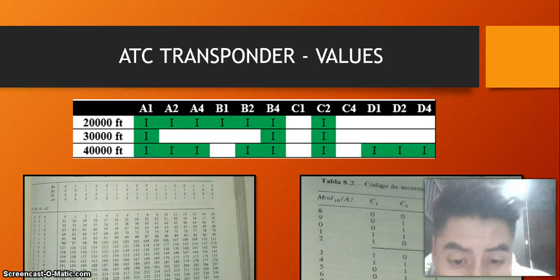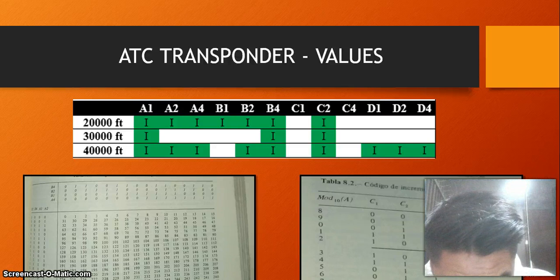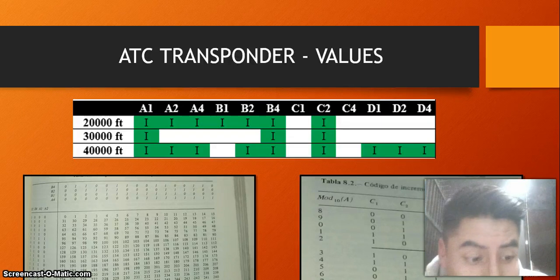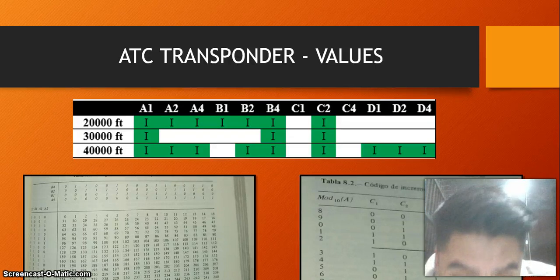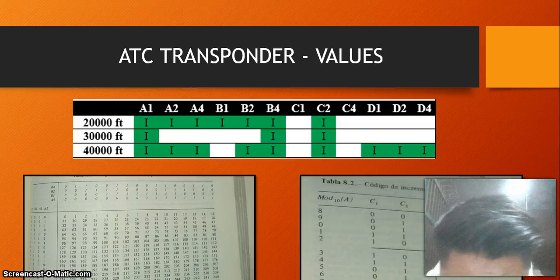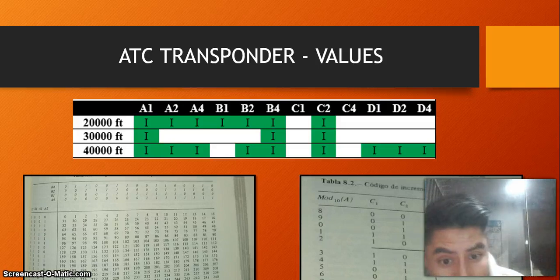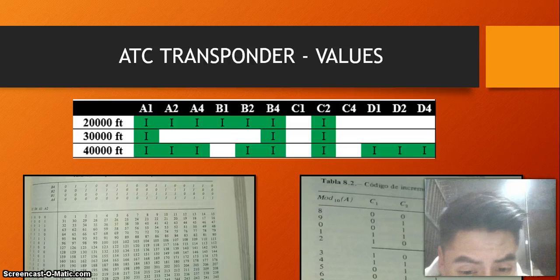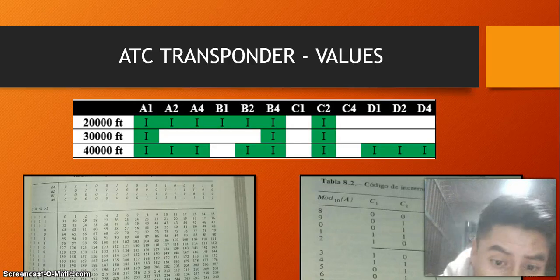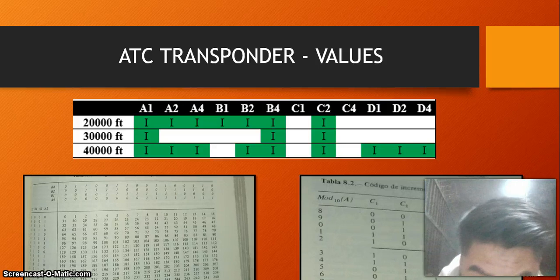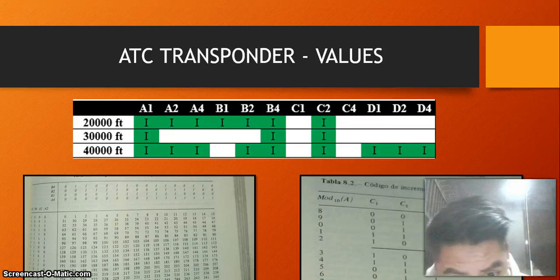This disk rotation transmits the altitude, and this information is detected by photographic cells. These digital signals are amplified and transmitted. The transponder receives them as pressure altitude. The computer converts this signal based on the local configuration for the altimeter.